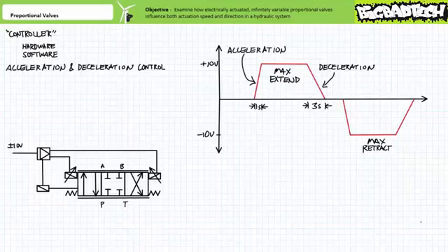It's extremely hard to nail down what a proportional valve controller is because it might be some independent physical object you can hold in your hand, or it might be some nebulous invisible entity you program, and is most likely a bit of both. Case in point being our earlier discussion on hysteresis. Closed-loop control of the spool position may already be integrated into the proportional valve, making the proportional valve itself part of the proportional valve controller.